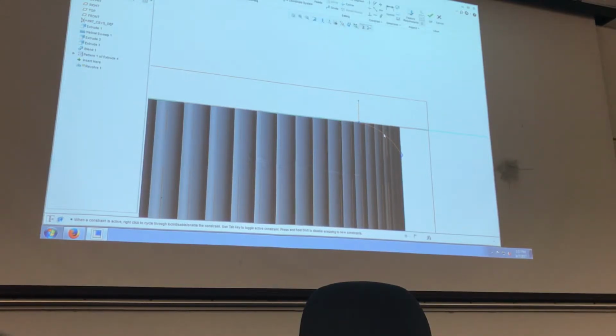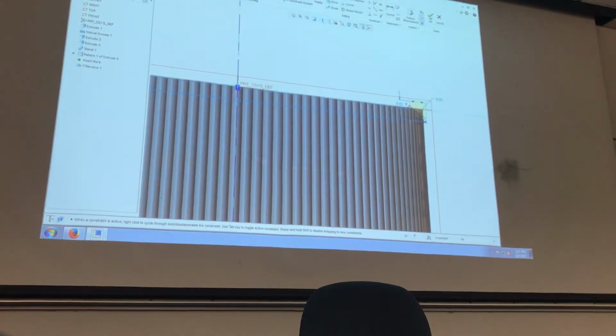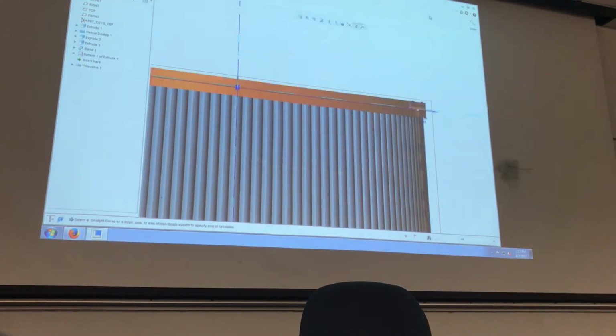And basically bring it up until I hit that perpendicular on it. Okay. Now, this constraint here, it's not going to be perfect. It'll be very, very close to it. Okay, but I'm going to go ahead and take another line from this point over. So I'm basically going to complete a solid form. And then that looks like it should work. Okay, it's showing it's trying to add. I remove material. Now it's showing me that, yes, it did work. I hit the check mark.